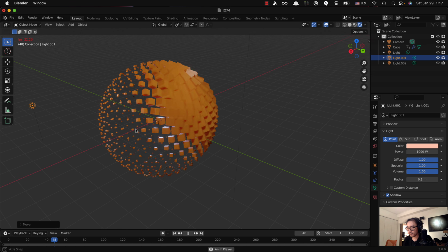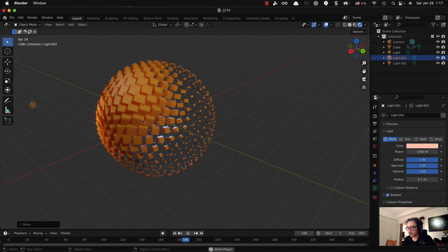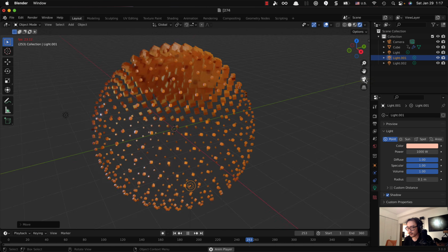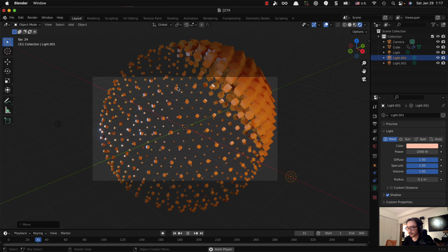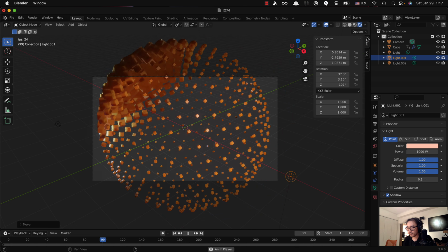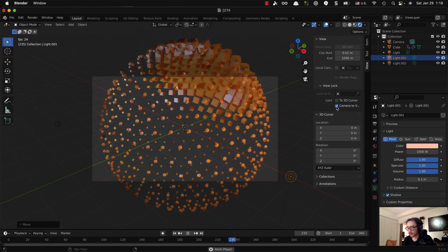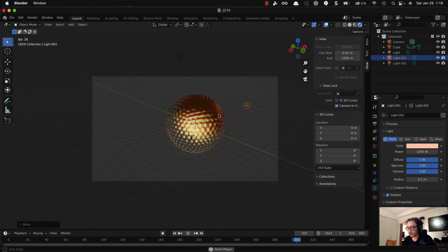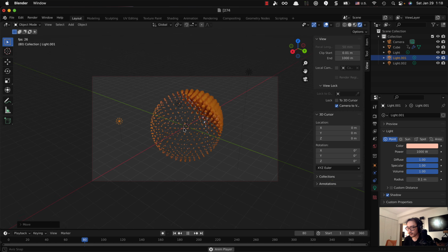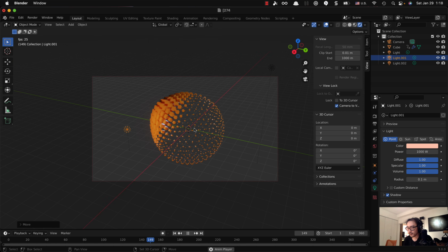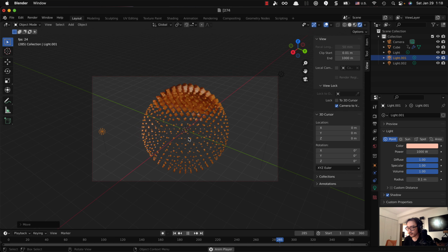Now, let's also set the camera in terms where if you want to do the renderings. So click this camera icon here, and you want to move this camera to have the best position. So show up this menu, go to the view and click camera to viewport locked, so that you can control this camera view by navigating the viewport. Okay, somewhere around here looks good, isn't it?